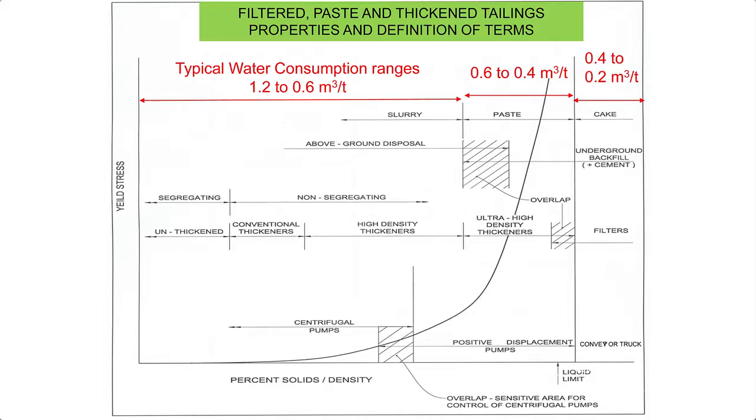However, there's a whole lot of things that are required to remove that water, and if you're into the cake zone, you're having to use filter type technology to do that. And once you start filtering your material, then you've got to start looking at how do you convey it, or how do you truck it to the disposal site, as opposed to using pumping systems, whether it's centrifugal pumps or whether it is positive displacement pumps. So these are the sort of things that you have to consider,